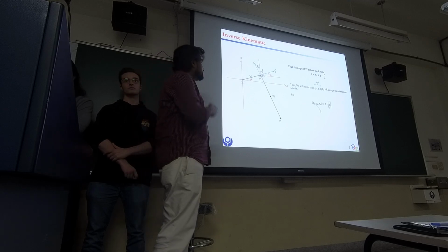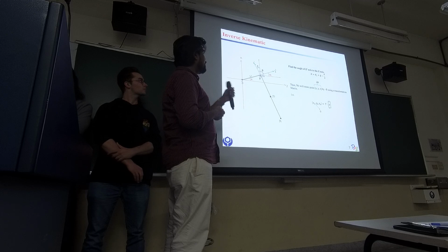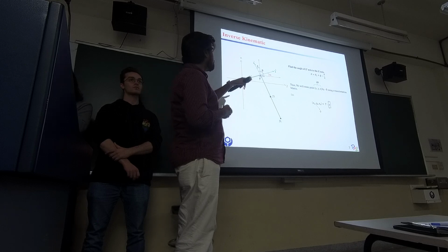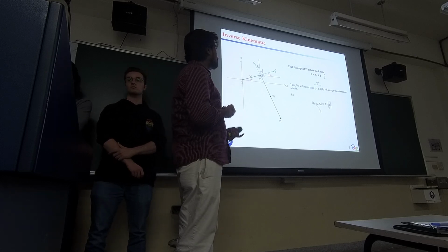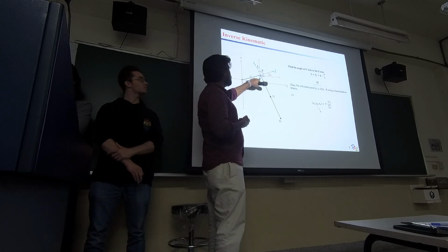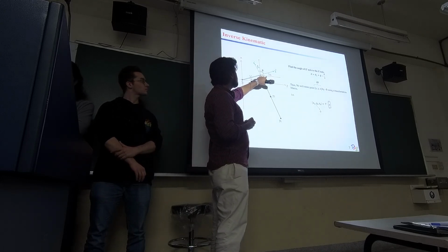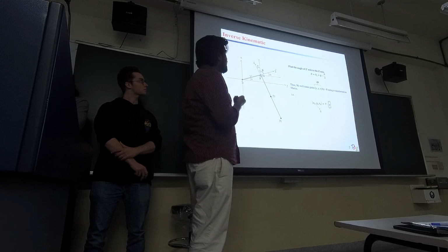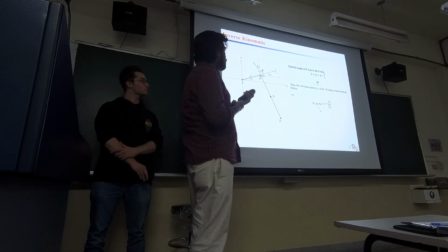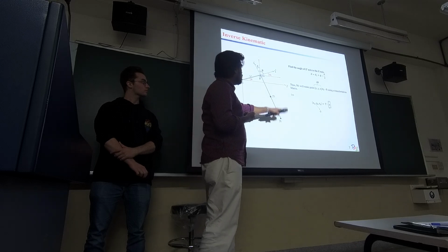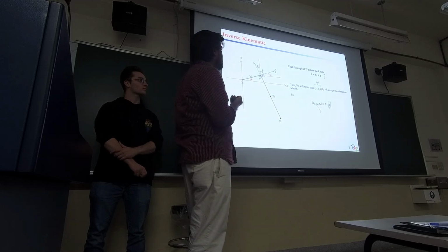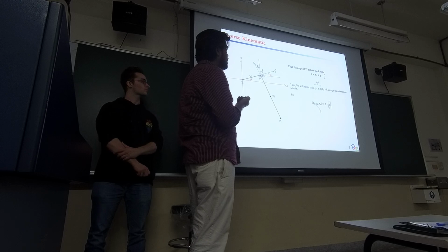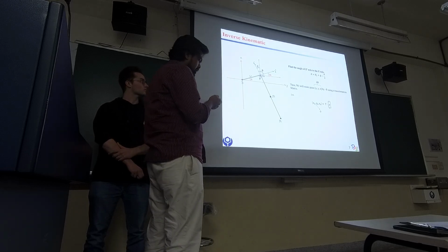Now we give some rotation to our coordinate. We give the minus r rotation to our coordinate and fix it to the next coordinate to make the calculation easier. So this is already in phi, so it moves to phi again, and we give the r rotation. This is the new coordinate, this is the previous coordinate. So we find the rotation matrix r. Then the new matrix will be the rotation matrix multiplied by the XYZ matrix.